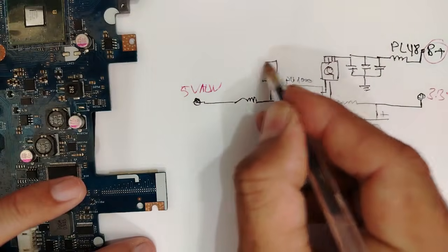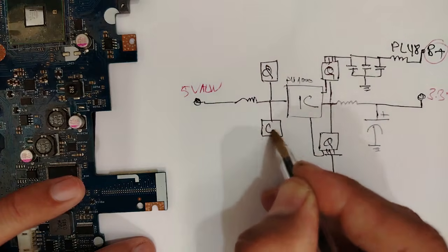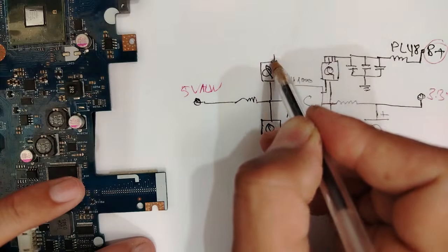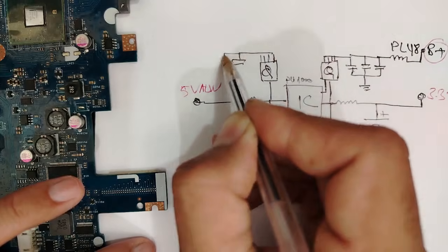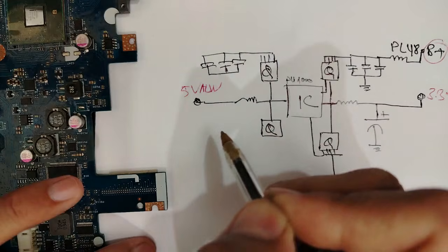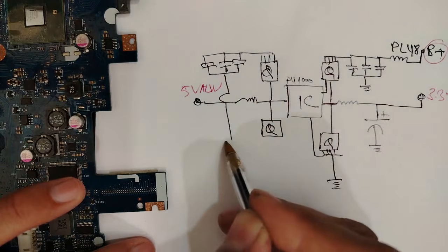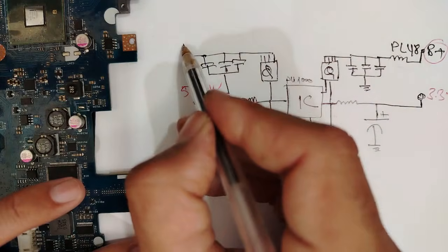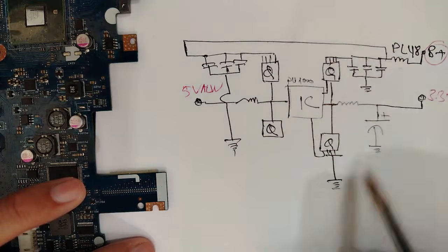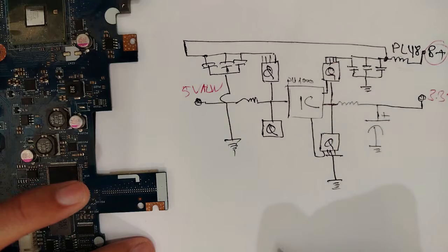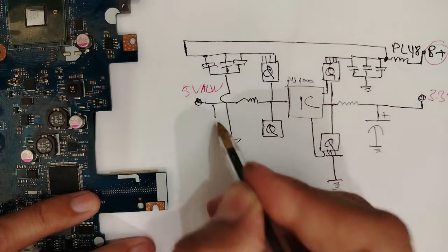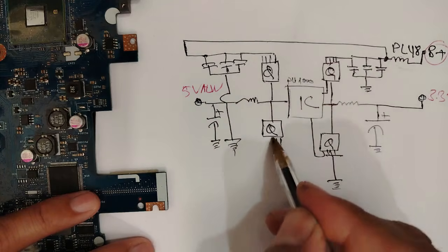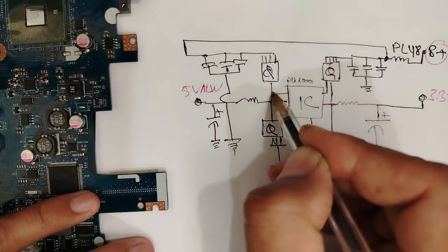And of course here we also have the second MOSFET. We're going to put the references after. Okay guys, we have the same B+ here. So the drain here is connected to 3 ceramic capacitors, all connected together and connected to the ground. And over here, basically we have the same inductor. And here of course we have the electrolytic capacitor plus, connected to the ground, and here we have the control signal.